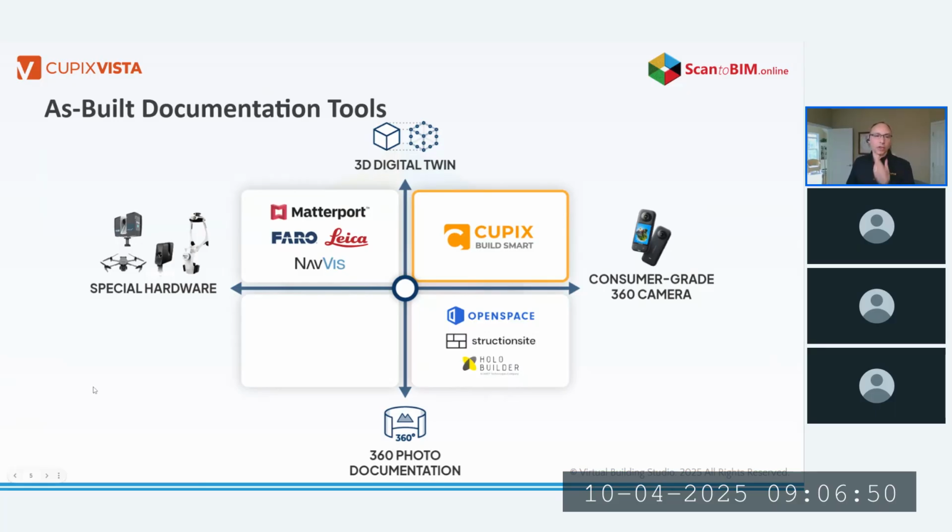So just taking a look at these tools, you have your terrestrial laser scanners. They have accuracy of down to the millimeter today. They are expensive and they can measure large volumes, but they take time because you have to set it up in every location that you need a line of sight from. Then you have drones. They're great for large areas. You can create orthomosaics. You can do photogrammetry from aerial. They take some training, although they're getting easier to use. But of course, they're not that effective for indoor use when you have indoor BIM.